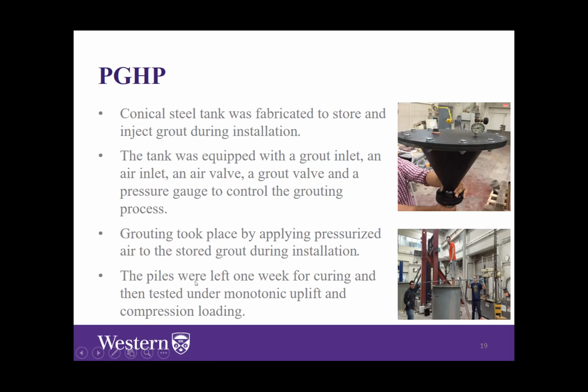The pile was left for 1 week in order for the grout to cure, and this 1 week was enough to develop about 80% of the compressive strength of the grout, or the f_cu of the grout. So we found that 80% is more than enough.